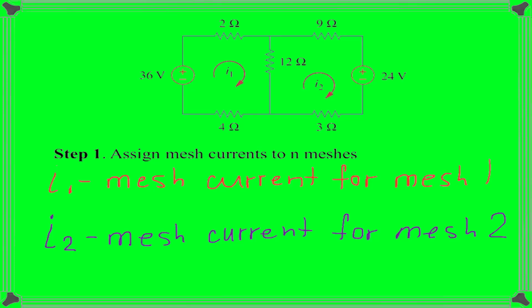So that means if you look at the current direction in each branch for mesh 1 and mesh 2, let's see where the current will flow. So in the first mesh, again going clockwise in the loop, here will be the direction of the current, and in the second loop, again the arrows point in the direction of the current in each branch around the loop.